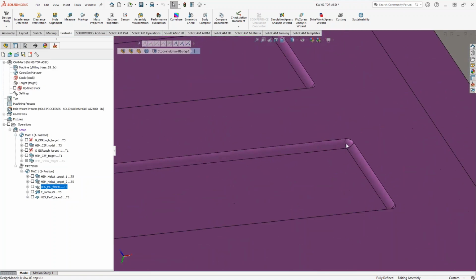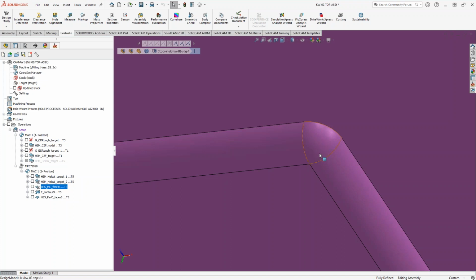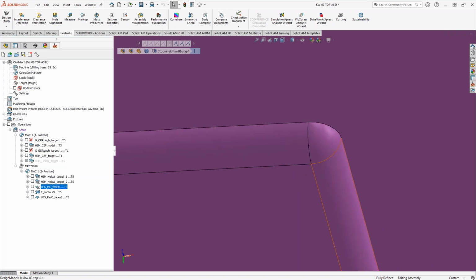And then with this guy, because of the size of the tool, I probably would stick with HSS, maybe just trying to account for it. Or I would try maybe the HSM, but HSM Helical, I mean, it ended up working, so I can't really say anything against Helical. It sounds like Kevin was surprised as well, but my first inclination would be something more like Constant Z or Constant Z Hybrid, or 3D Constant Step Over, maybe to get that same sort of movement there. Yeah, but if you're looking at 3D corner offset.